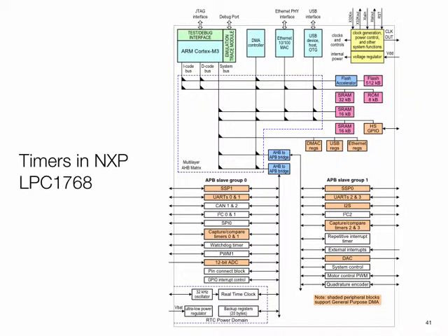Timers and counters. These things tend to have a pretty elaborate system in terms of how the application gets to make use of these clocks. On the bottom side of the slide, you see things like capture compare timers and repetitive interrupt timers. So there are a bunch of different kinds of timers that this microcontroller typically provides so that the OS and the software can use them.